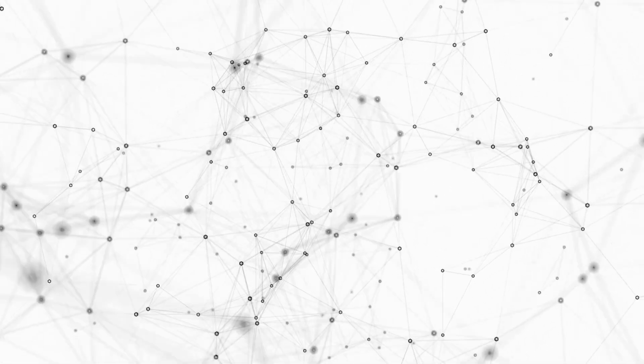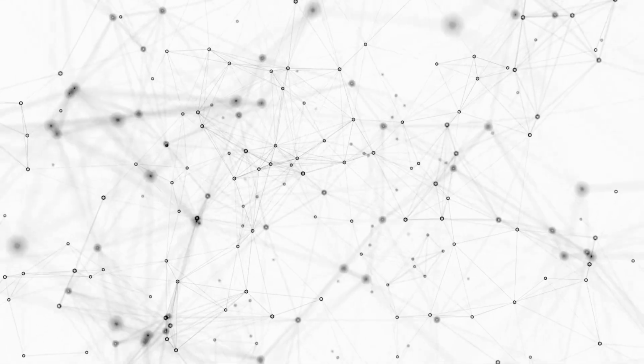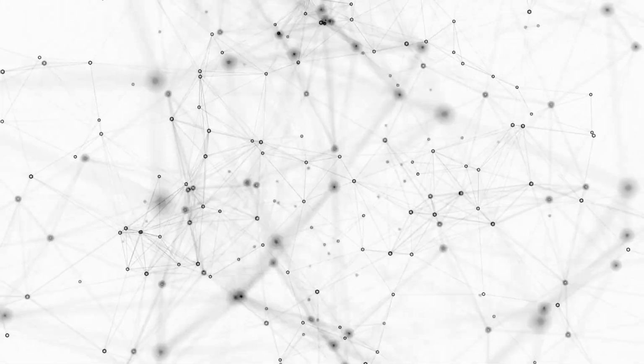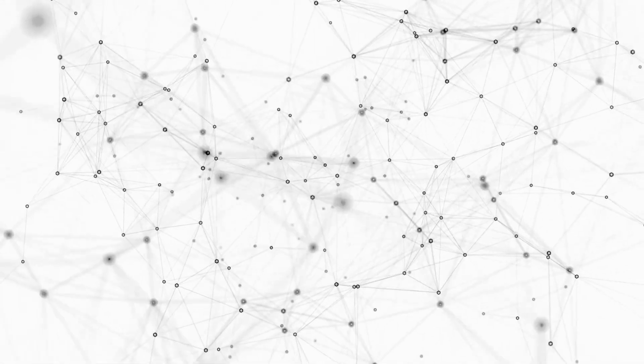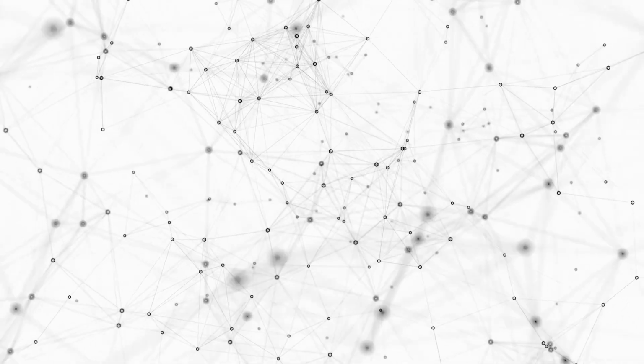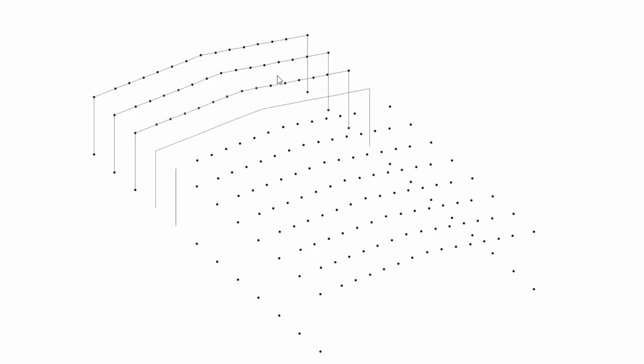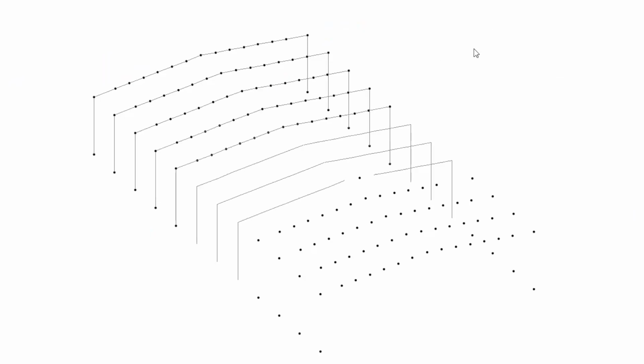So far, we have seen around 7 to 10 OpenSTAAD functions, I guess, in this series. If I say that we can create a complete 3D model making use of only 2 of these functions, would you believe that? Even if you won't, that is the truth. The 3D model generation tool which you are watching now makes use of only 2 main OpenSTAAD functions, and they are create node and create beam.